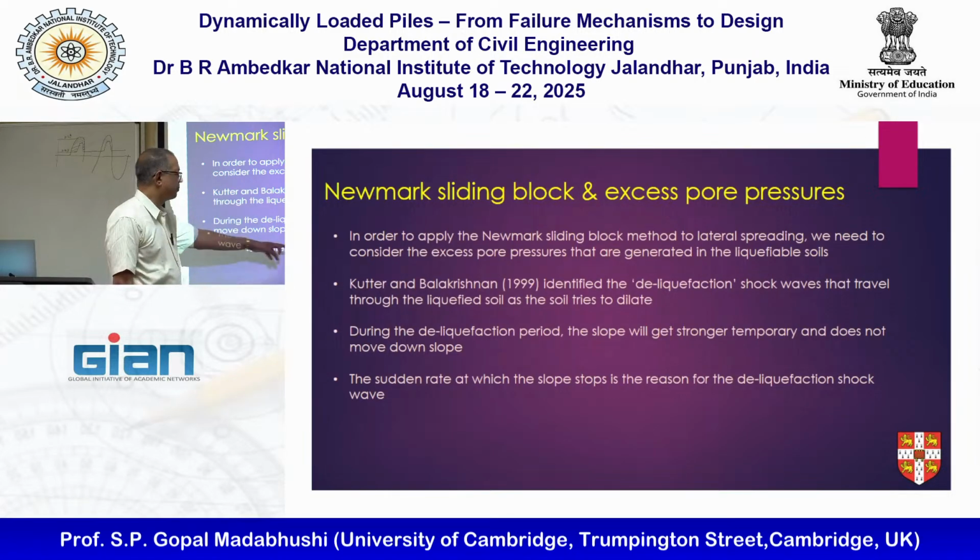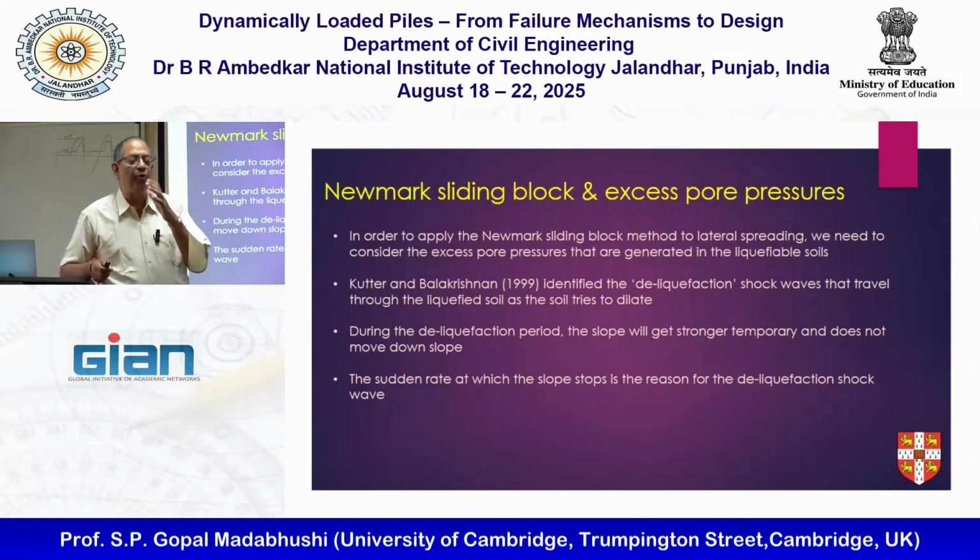And this also explains why in the centrifuge tests and experiments we do, we see the slope suddenly stops and then moves and stops and moves as well. And it's all linked to pore water pressure.